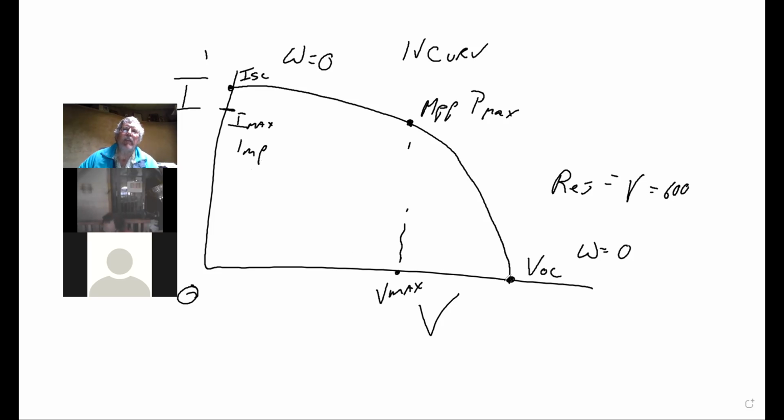Yeah. Now you can measure the VOC. If you were to take a solar panel and put a voltmeter on the positive and negative leads with no load attached, you will get the open circuit voltage. That's what I understand, open circuit. But the ISC, I have a feeling it's a bit like absolute zero. It's a theoretical number, but you can never actually get there. Yep.